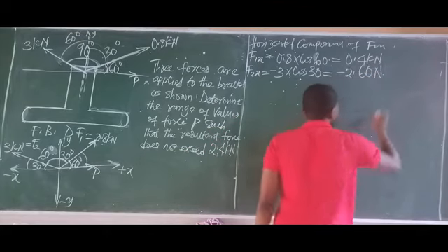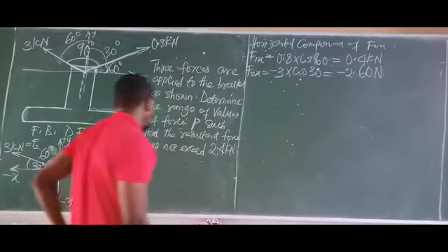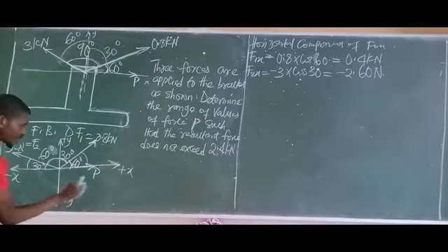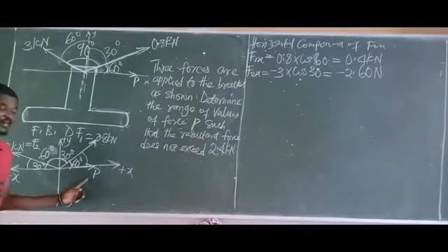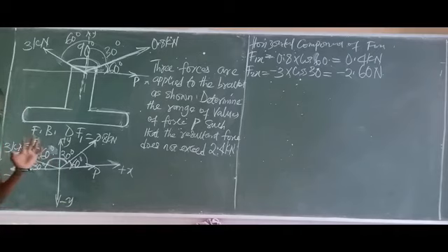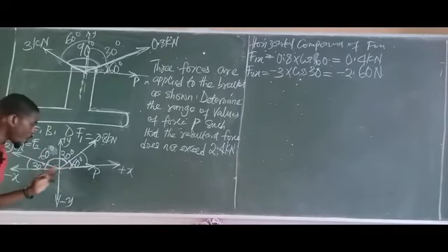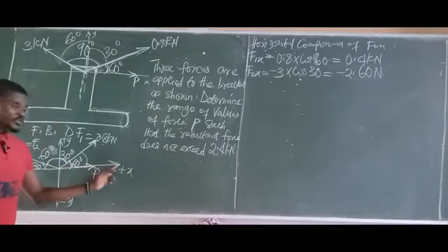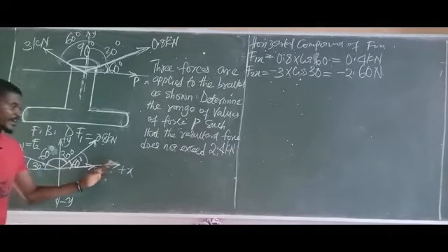2.60 kilonewtons. And finally, we need to resolve force P in the X direction. Notice now, please be very careful that P already is in the X direction. Already P is in the X direction.